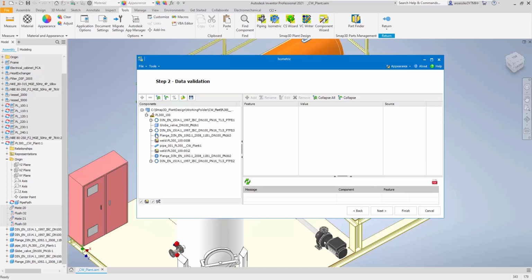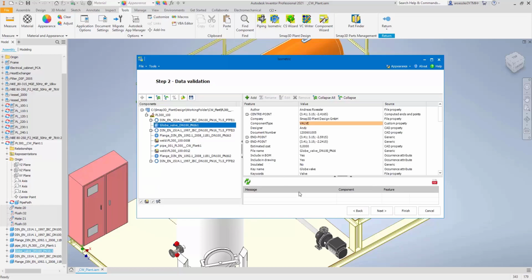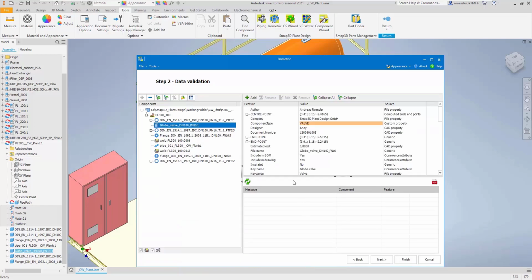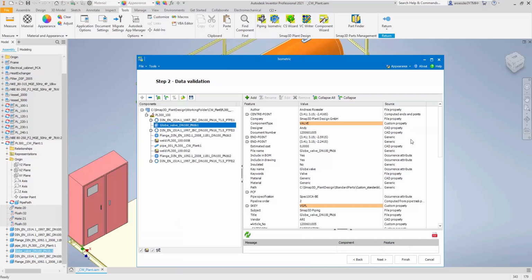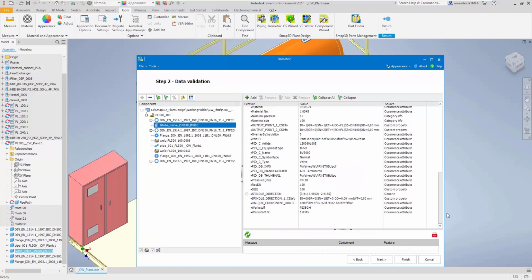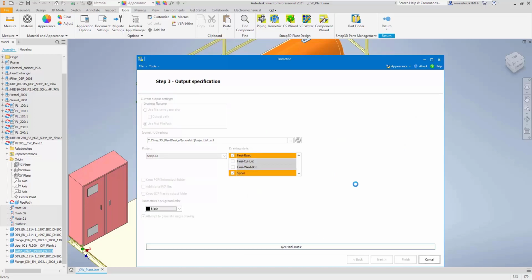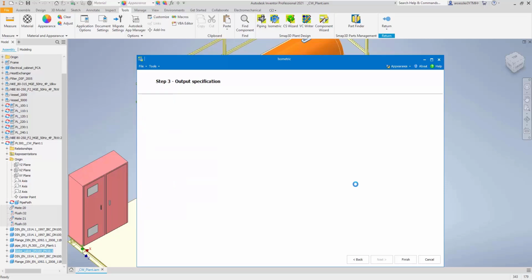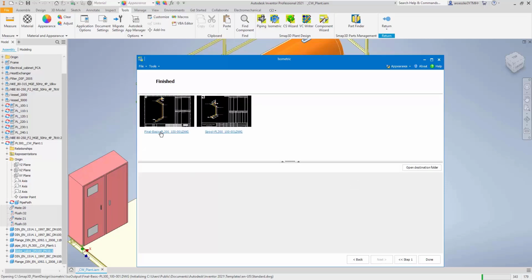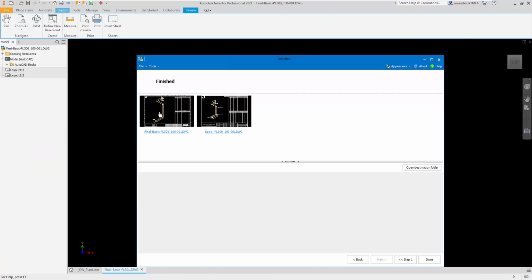All of the piping and instrumentation data is pushed out to a PCF file. Subsequently, different templates can be selected, resulting in different layout options. This determines how the production-relevant information is mapped on the isometric drawing. The finished drawing can be output either as DXF or a DWG.